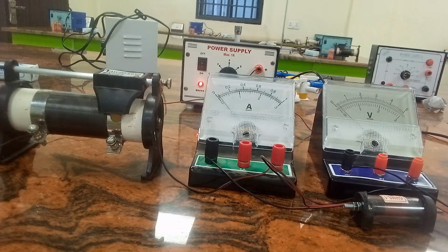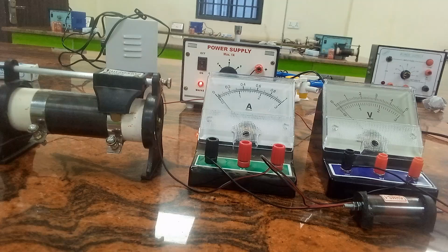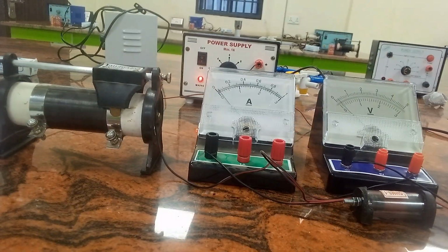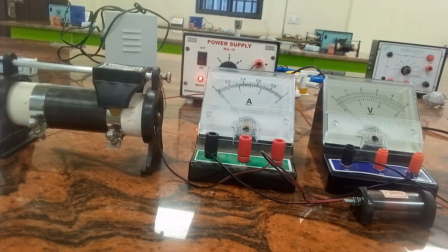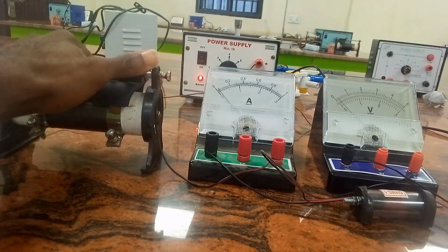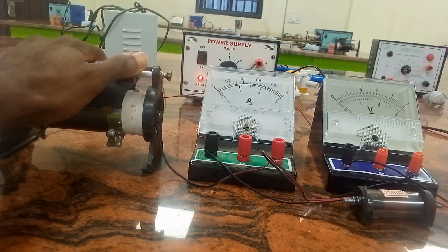So as a beginner, at first I'm going to record the initial reading of the ammeter and the voltmeter as my number one. The next thing I'm going to do is, using my variable resistor, slide the variable resistor to 3 different points. I'm going to slide it gently and observe the variation. So I'm going to make my first slide at this point here.